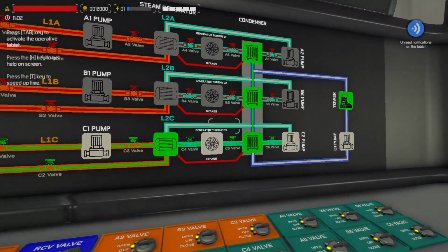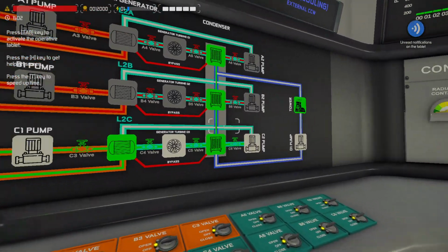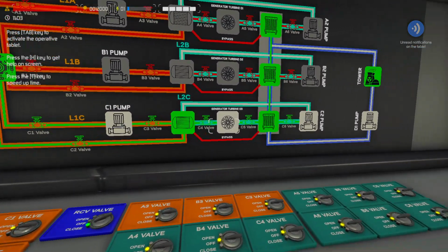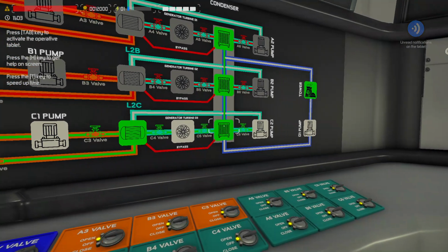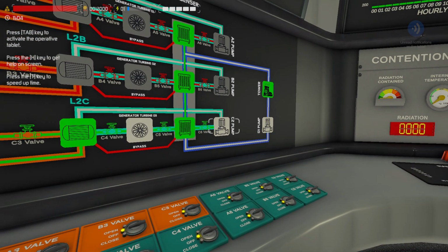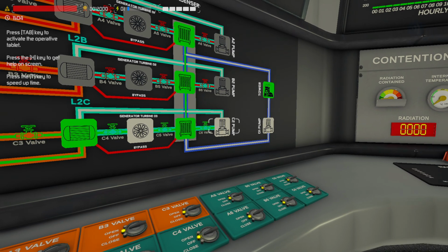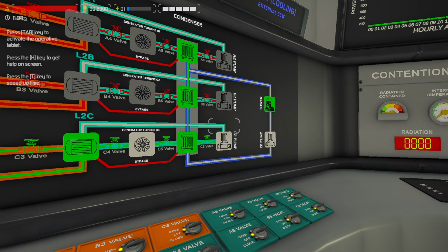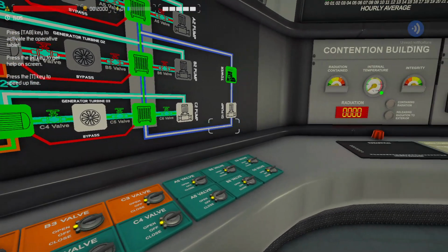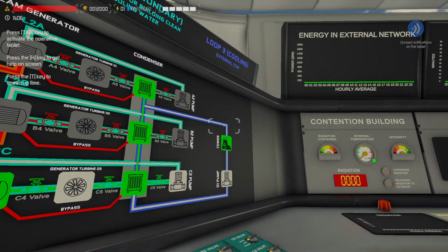So this side, the steam generator side, this would all be chemically treated water to prevent corrosion here, and then prevent corrosion here and in here, and your pump as well. So this water would be chemically treated, so you can actually get longer life out of your components. And that's why you don't want to use this water, which is open to the atmosphere.